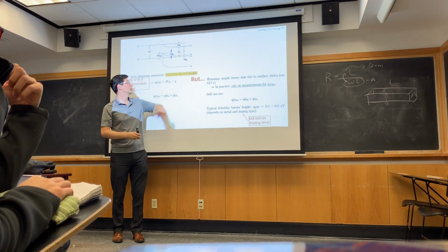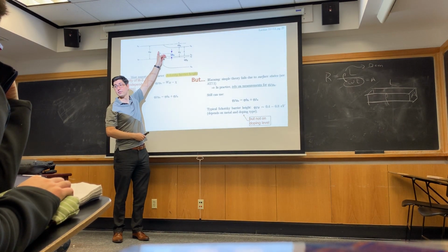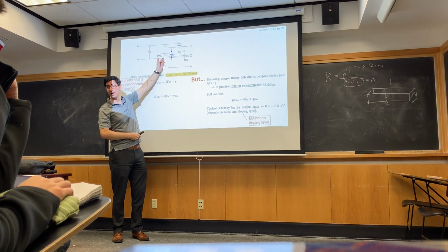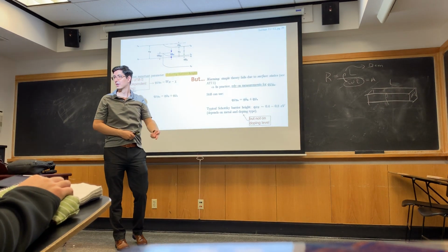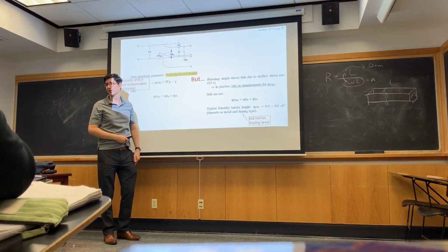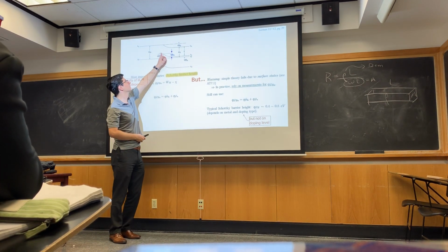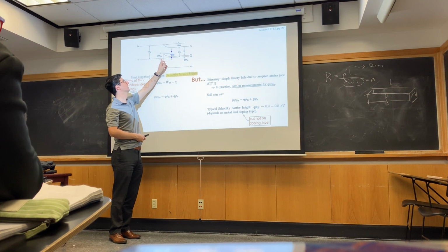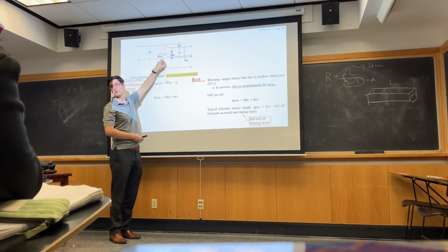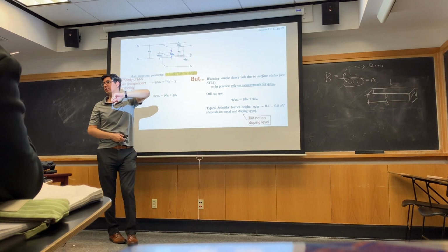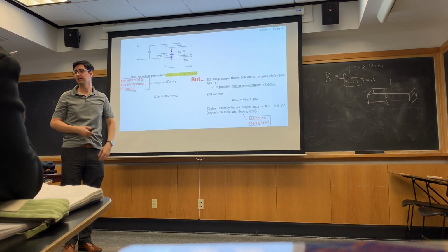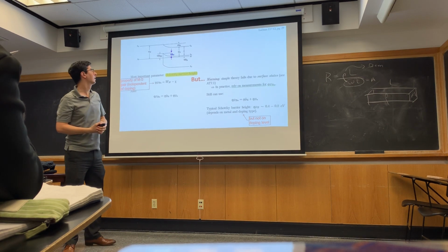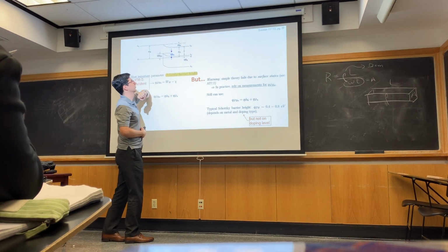I know how many electrons there are at 0.6, right? That's 10 times 60 millivolts. So that means I have 10 to the 10 fewer electrons at this point compared to my Fermi level, if that barrier height is 600 millielectron volts.